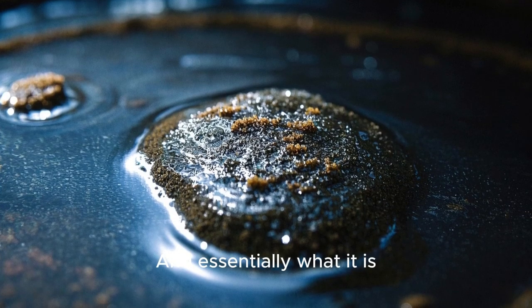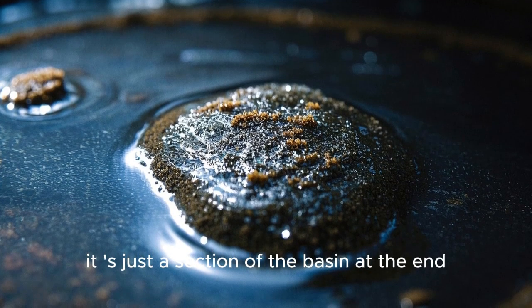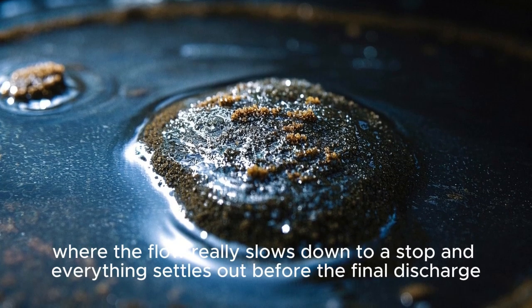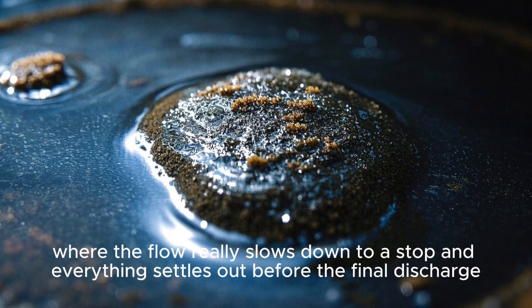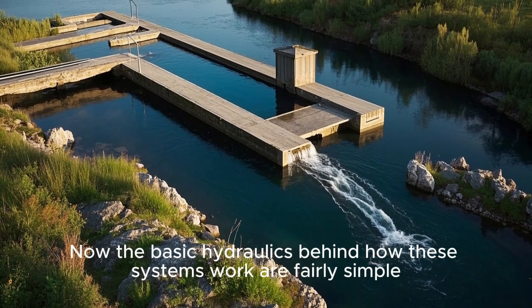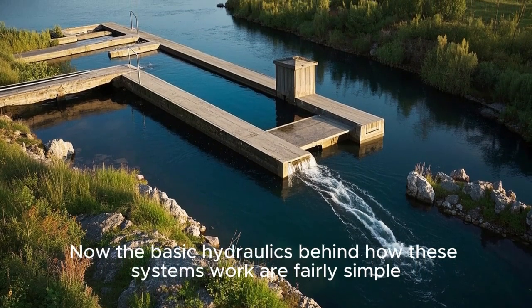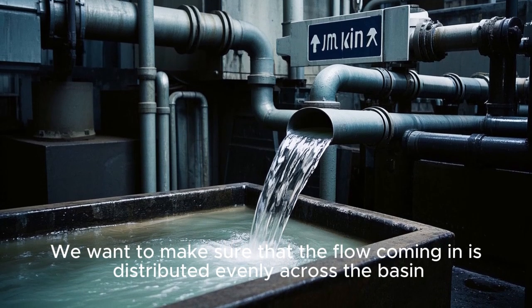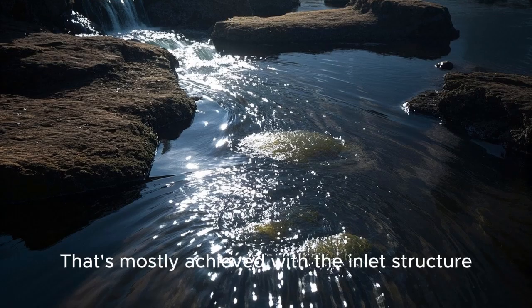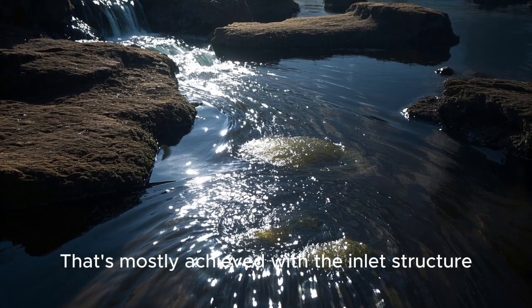And essentially what it is, it's just a section of the basin at the end where the flow really slows down to a stop and everything settles out before the final discharge. Now, the basic hydraulics behind how these systems work are fairly simple. We want to make sure that the flow coming in is distributed evenly across the basin. That's mostly achieved with the inlet structure.